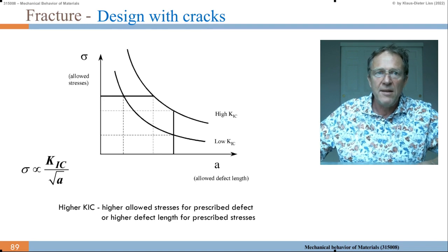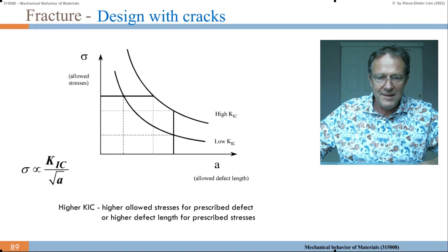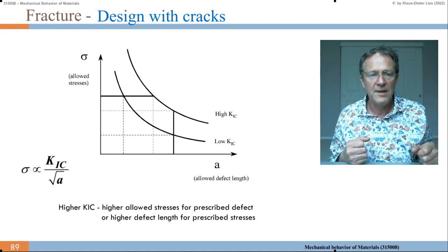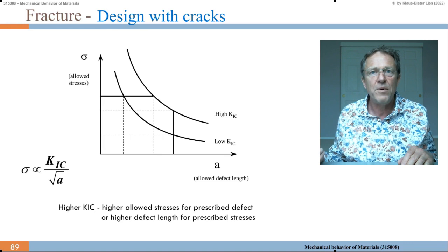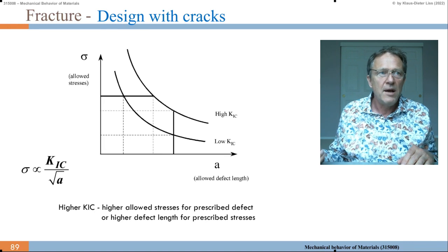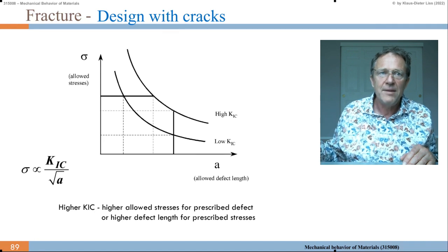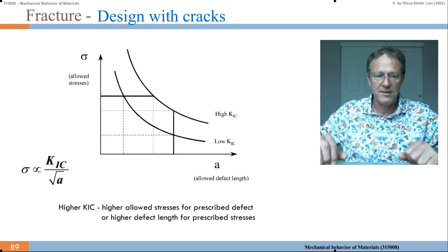The engine, high temperature materials, they have creep. Later on in this lecture, we will talk about creep. This is where the material becomes longer at high temperatures in the turbine, and the turbine blade does not last forever. After some lifetime operating hours, it will lead to failure. So we have to design when the machine has to be serviced, when these parts have to be replaced. And the same is for the cracks.